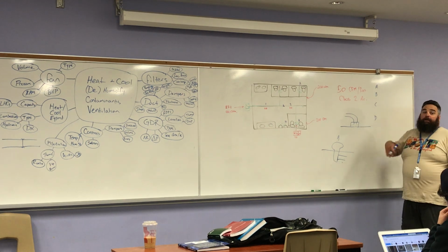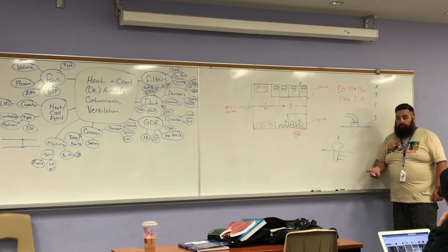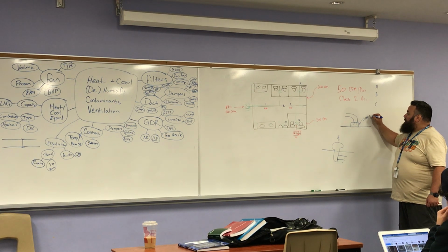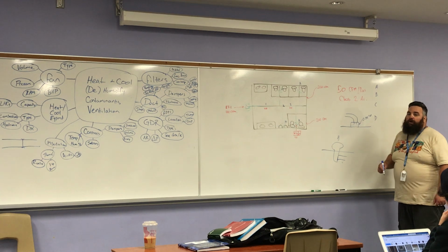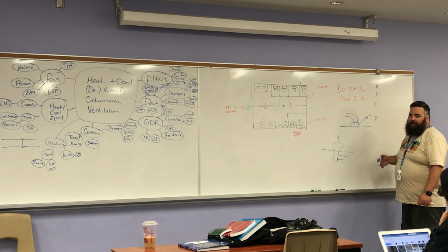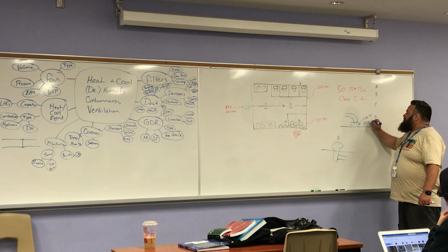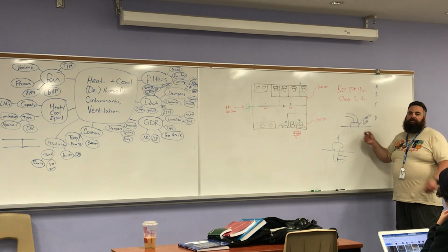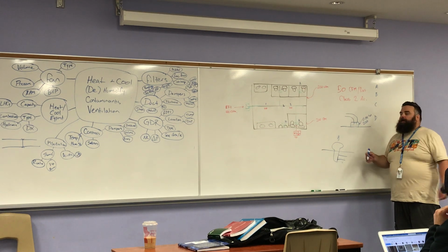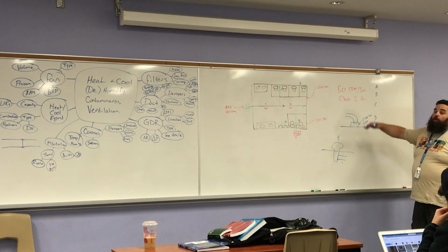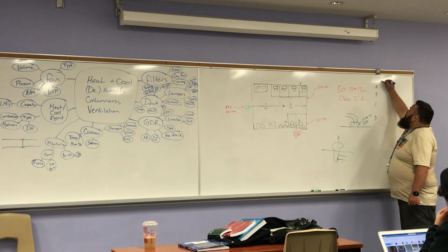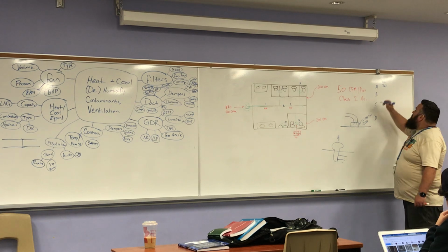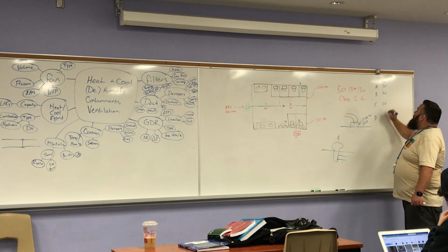So we can look at either a pressure drop in inches water column. So maybe this is 0.04 inches water column, or we could even go as far, depending on the residential way we did it, we could say that has 20 feet of equivalent length. That friction loss is the same as if we had 20 feet of straight duct. Okay? So you identify this and you record it all. So let's say our terminal is 20 feet. They all have the same terminal. So you take 20, 20, 20.